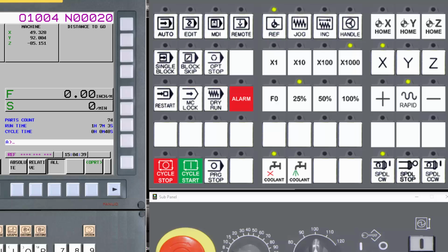Today's battery-powered absolute encoders monitor axis positions even when the main machine power is off. Even if an axis is moved mechanically, the feedback device detects the new position. Now the only time the axis needs to establish a reference point is during installation and then whenever the batteries are replaced with the machine power turned off. The reference position is often referred to as home or the home return position.